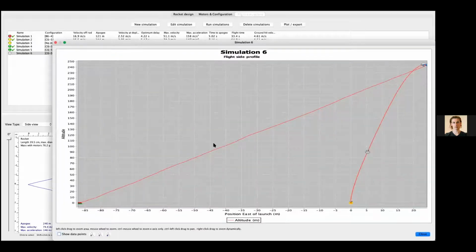All right. So we can see here that on the right-hand side, the little explodey icon is ignition. The rocket is going up for about 100 meters under power. That little puff icon is when the motor burns out and stops firing. And then the ejection delay begins from there.